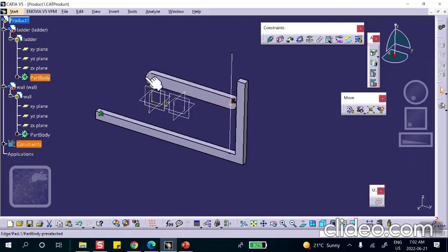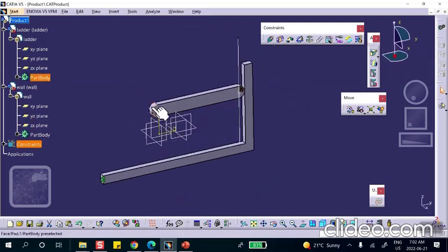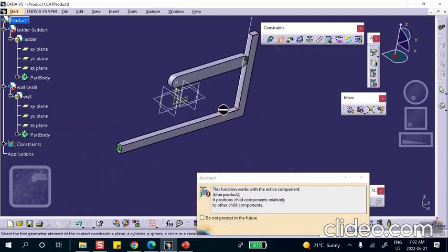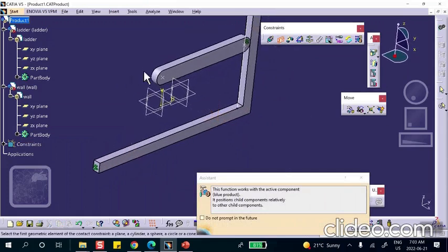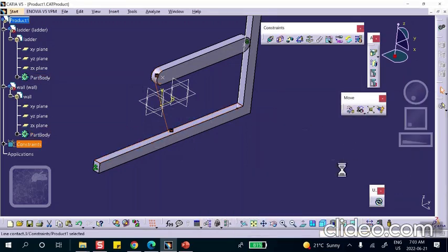Okay, good. Now this, I want to bring this surface and put it on that surface. And the way to do it is by using the contact constraint that we have not used so far in the course, in this part of the course. That's not the same contact as FEA. So that face and this face, notice that there is external and internal. This means that they're externally going to be contacting each other. If one doesn't look good or doesn't look right, change it to the other one. But I'm sure it's going to be okay.